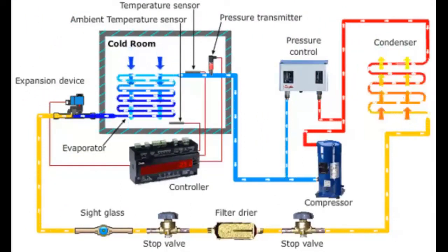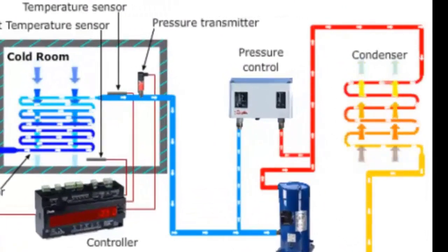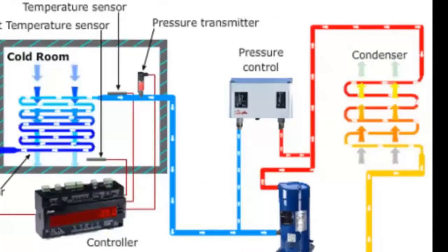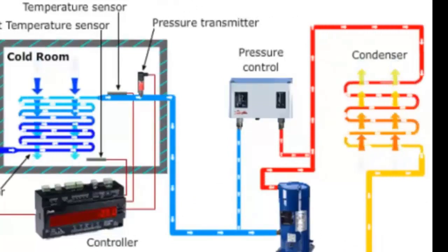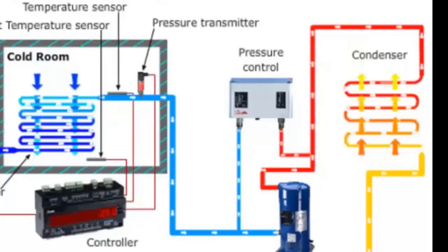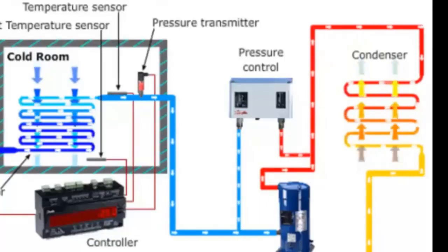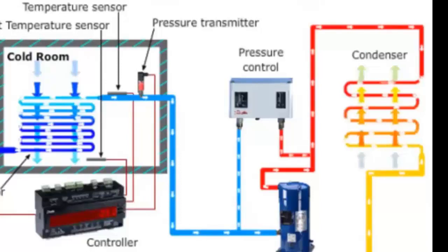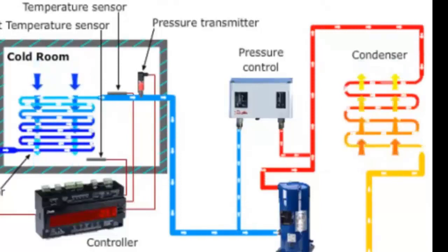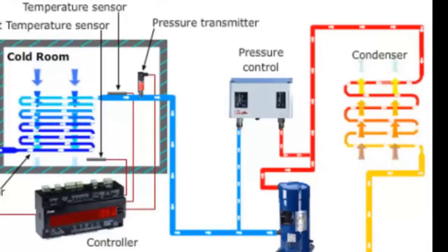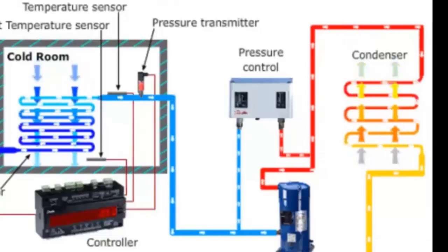Additionally, we observe the control and safety mechanisms. 8. Pressure switch to stop the equipment due to low pressure in the compressor suction or high pressure in the system discharge. 9. Pressure transducer for suction, used to inform the electronic controller of the cold room about the pressure value.